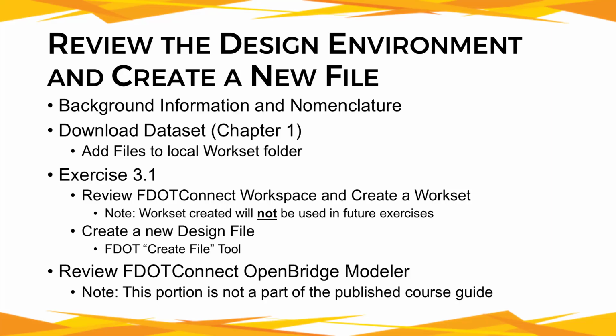This is the first video in the Bridge Design 3D Modeling and Plans series. Since it's the first video, we're going to go over some background information and nomenclature, as well as download the dataset before we jump into exercise 3.1. We'll go through exercise 3.1, where we'll practice creating a work set, and then we'll create a new design file using the FDOT Create File tool. After the exercise, we'll take a moment to go over some basics of the FDOT Connect software within OBM.